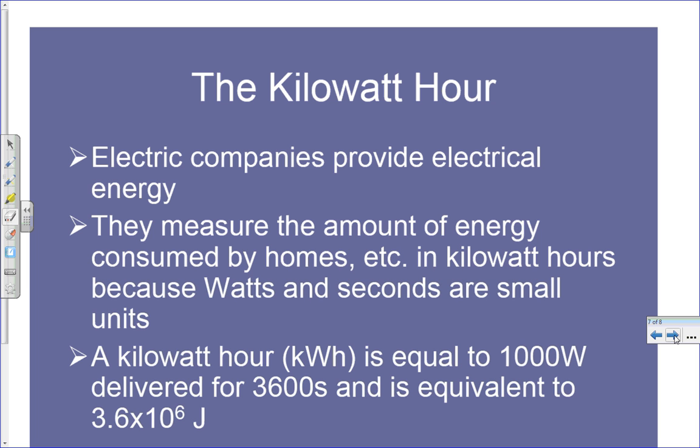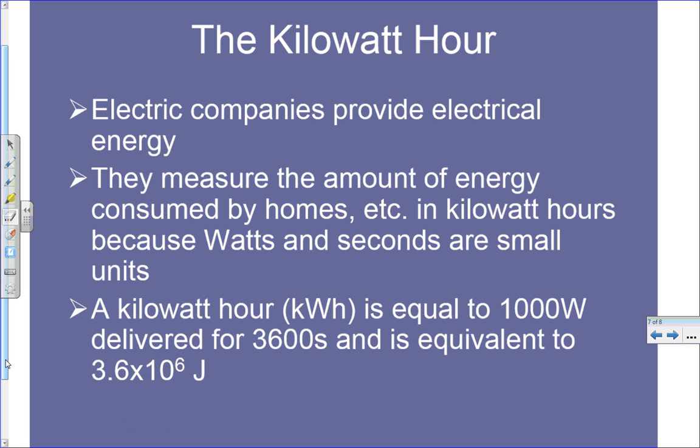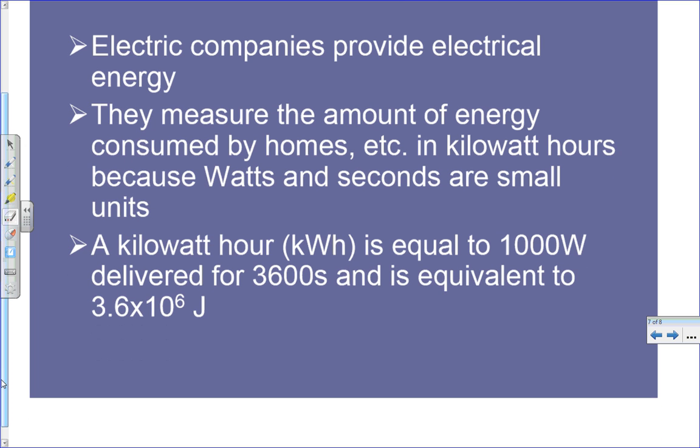And lastly, the electric energy companies provide us electrical energy. They don't provide us power, they provide us electrical energy. They measure that amount of energy in kilowatt hours, because watts and seconds are very small units. So a kilowatt hour is equal to 1,000 watts, that's what a kilowatt is, delivered for 3,600 seconds. So that's equal to 3.6 million joules of energy.